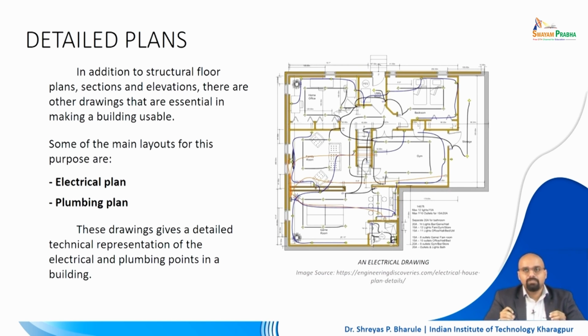All of these wirings are also to be connected to certain switchboards. So how will a layout work? For example, sometimes in the case of a bedroom, you also require double switches, meaning there will be one switchboard right next to the entrance of that particular bedroom. Also on the bedside, you will have additional buttons which do the same operation of switching on or off the lights or the fan inside that room, right? So these kinds of additional fixtures also require this information to be provided for the people who will be executing this particular plan, right?